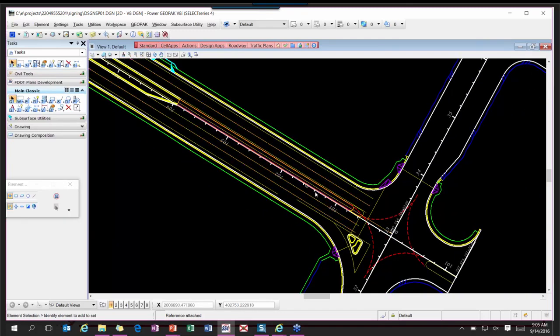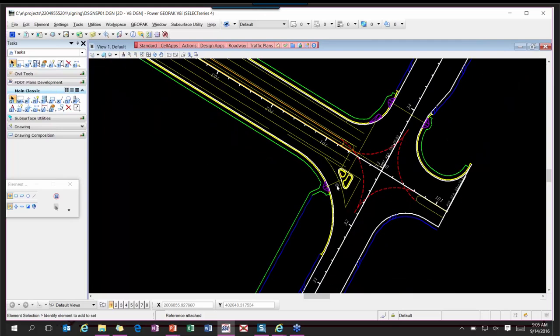We'll have a left turn lane as well as we're going to transition the bike lane over next to the travel lane, and then you're going to have a right turn lane that's going to come in here between the edge of pavement and our island. Okay, it is a signalized intersection, so we're also going to come in here and put in some special emphasis crosswalks. So that's the basics of what we're going to try to get in here today.